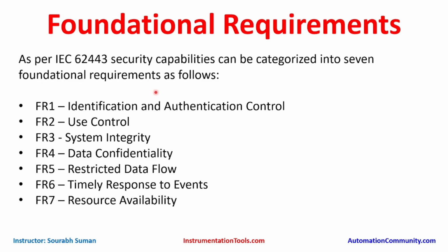So basically IEC 62443 assists in the evaluation of existing and potential vulnerabilities within ICS and aids in applying the necessary mitigations. So the goal of this standard is to reduce the risk of threats and failures within ICS networks. The standard consists of 13 documents, which are grouped into four groups: general, policies and procedures, system, and components.